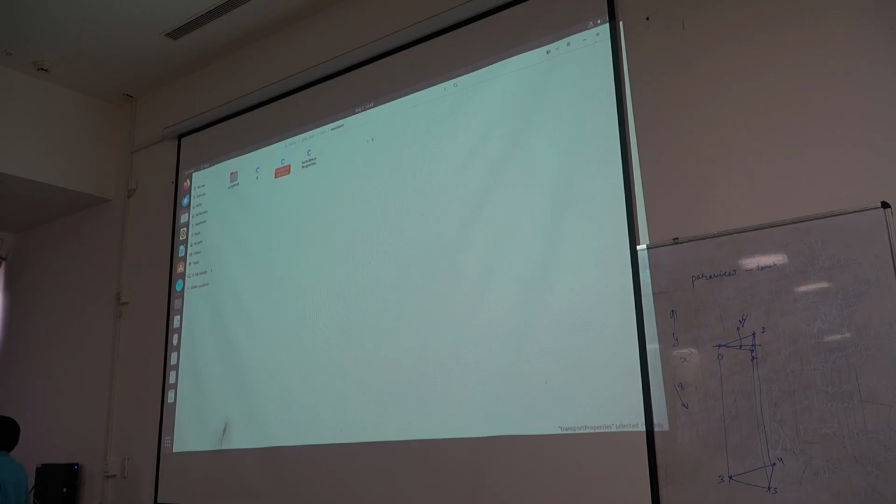Now after this, I will go to turbulenceProperties, and the simulation type is laminar. I need not do anything because this is a low speed flow. I am not interested in turbulence.